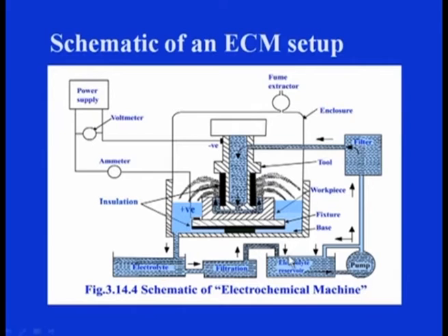Then the electrolyte will be continuously kept flowing with this electrolyte pumping system, which is in fact a complex system in which several stages will be there, where the electrolyte will be filtered, so that the debris produced during the machining does not get circulated again into the gap.